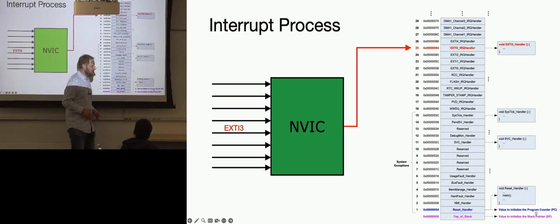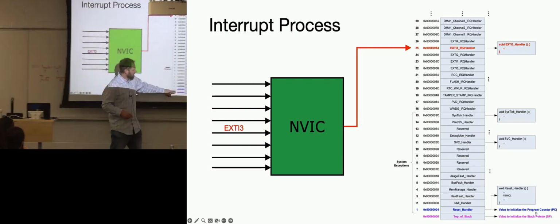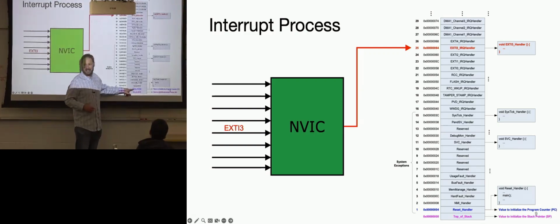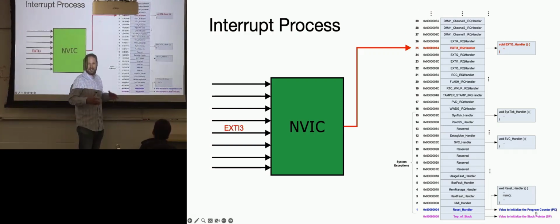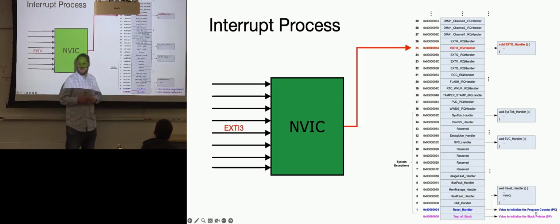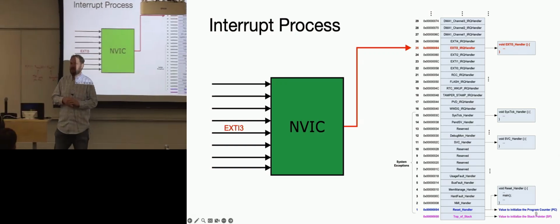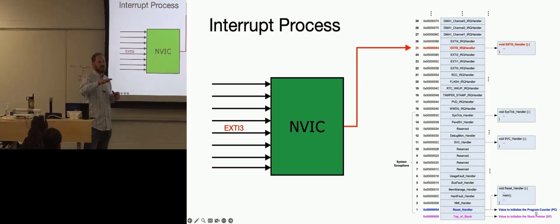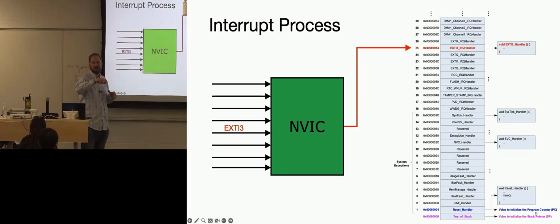What happens when this fault occurs? Typically, for you guys, you're going to worry about the reset handler. That would be a thing that you want it to boot up in a certain state. I've certainly written programs where in a reset handler, you want to make sure the state of certain pins is known. So you don't want it to boot up and have the default state of LEDs. You want it to be a known state. Those sorts of things.